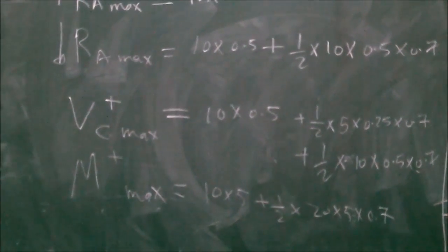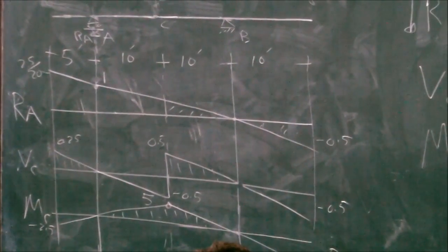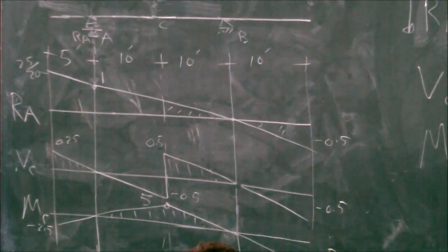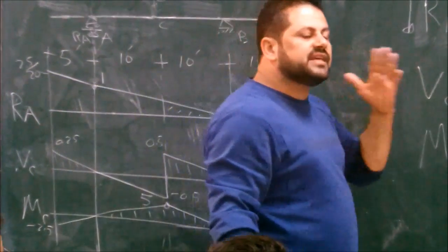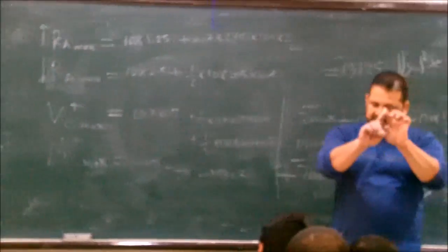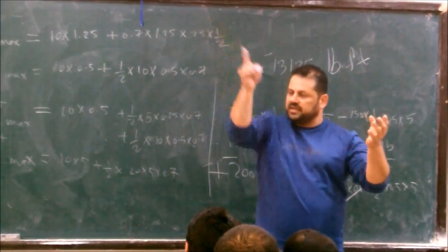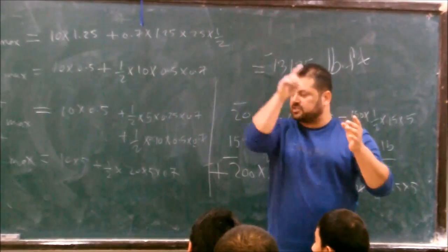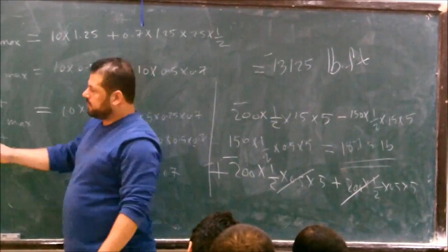So you construct the influence line, you place the load to maximize. The influence line for a determinate structure is straight segments. In segments with continuity, meaning no change in load or support, it is a straight line. It doesn't change the slope. Good. Any concepts?